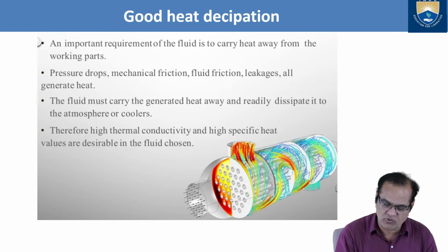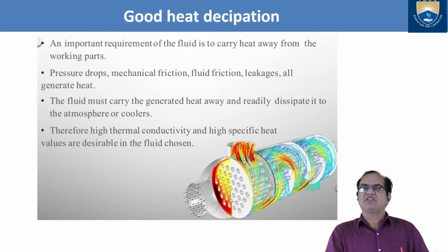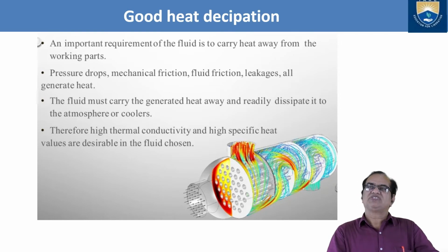So wherever you want to lubricate or you want to use this fluid, whatever heat is there, it should be able to take away. Pressure drop, mechanical friction, fluid friction, leakage, all generate heat. So if the pressure is dropping, it will generate heat. If the mechanical friction is there, it will generate heat. If there is friction between the fluid, there will be heat. If there is a leakage, heat will be there. All of these generate heat.